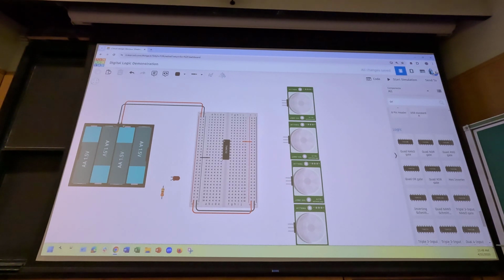Seeing a lot of green wires, I would recommend color coding. Makes your life a lot easier. Black for ground, red for power, and then green for signal, or different signal color for each of the sensors, whatever you want to do. But if you leave everything green, it gets messy.